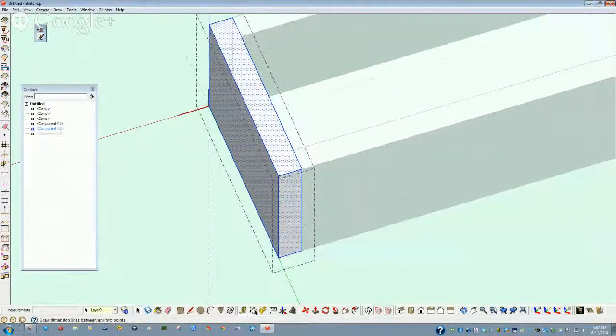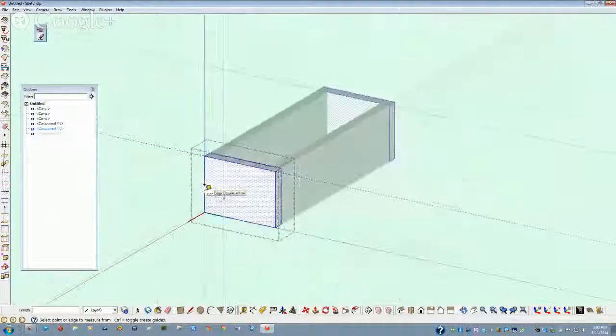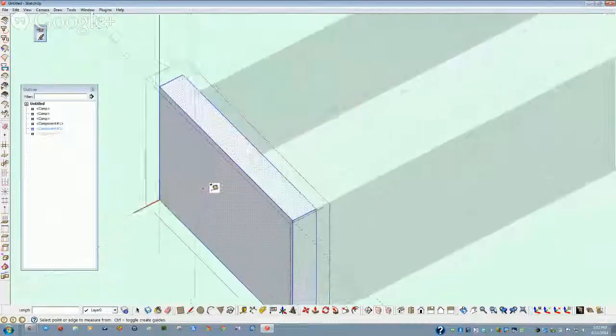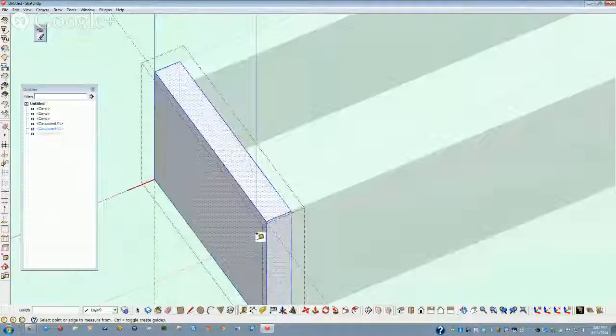The tape measure tool and the protractor tool. First, in the tape measure tool, if you come up to an element and double mouse click 1 on it, we'll get an infinite dashed line saying, okay, this is a guideline, which is exactly what it is.